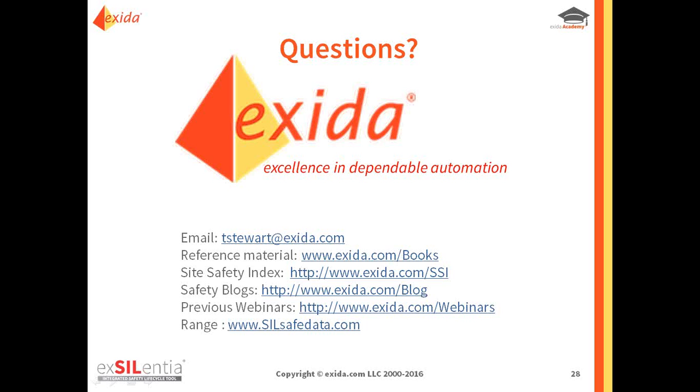If failure rates from the component database that exida uses and the FMEDA are validated with field data, why do we want operators to collect failure data? That's a good question. The key answer is that if you collect data, you'll be able to identify and sort the differences between product-specific failures and site-specific failures. So that's the biggest thing. And if you have a good process and yet you still find failures higher than they should be, now you know you have a problem. But it's a problem you can fix.